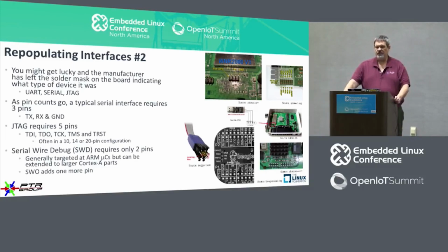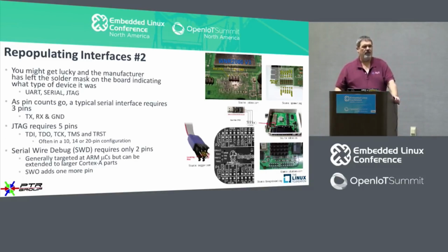Now, some of the manufacturers will actually blow the E-fuses. So what the heck's an E-fuse? An E-fuse is an electrical fuse that's on the chip itself, and when they blow the E-fuse, it basically breaks the connection to the debugger. If they've blown the E-fuses, the only way to fix those is to decap the chip, and with a laser, you spot weld the E-fuse back in place. That clearly is not something that the typical user has at home.